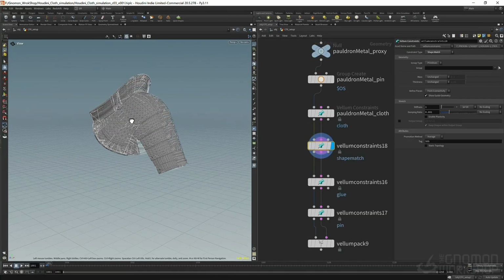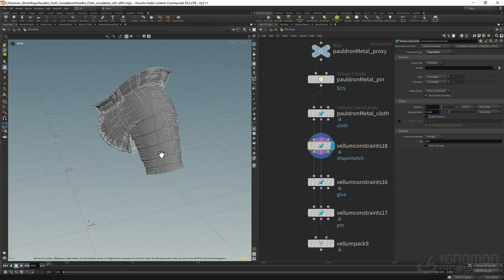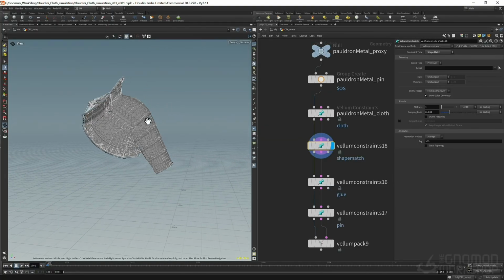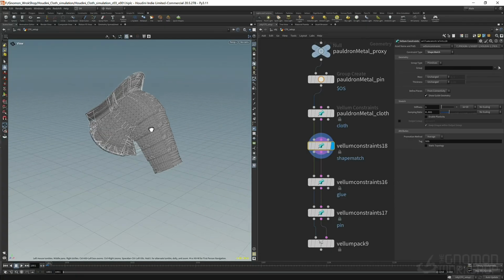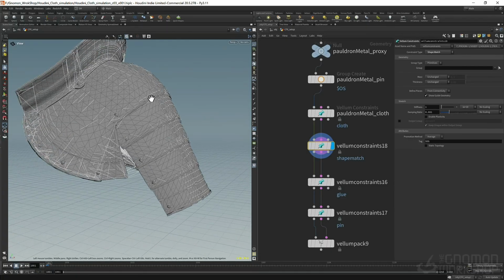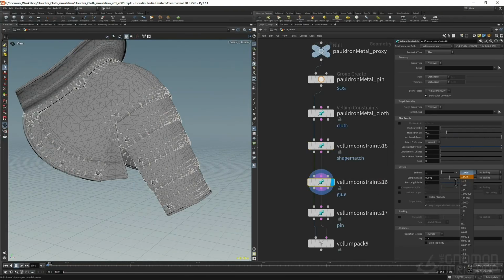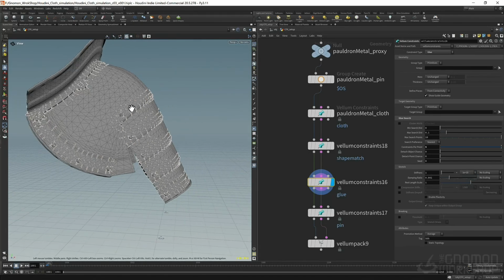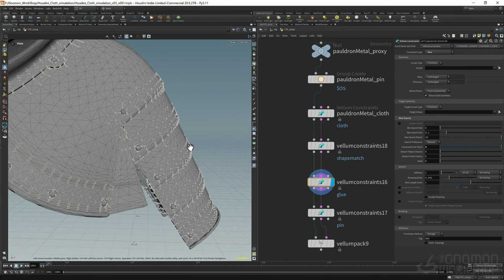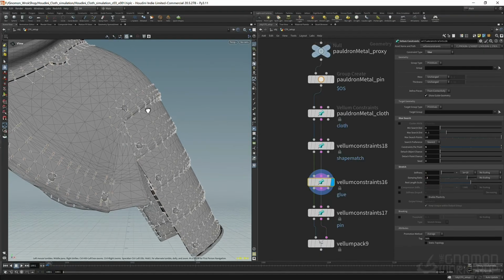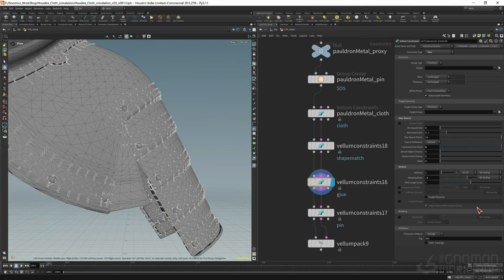But it depends on your simulation, how intense the colliding or the stress on this object is. For example, this one, in the animation, is bending too much. We'd like to keep the original shape with a little bit of bending in between the pieces. With that, we have a glue. We can decrease the stress stiffness in this, for example, or we can increase the damping ratio. This way we have a little bit of freedom between the pieces, so it can feel like it's bending, but this will keep it for later.